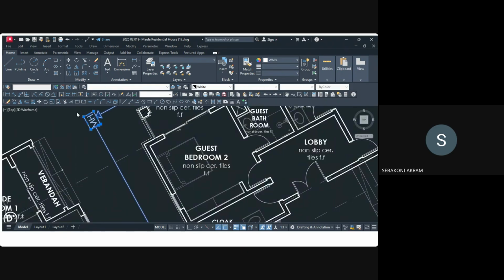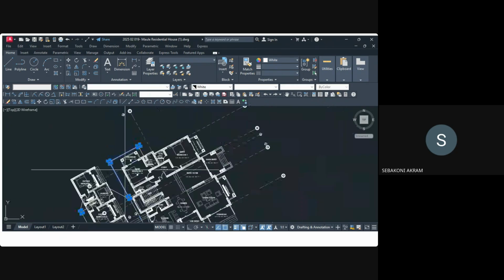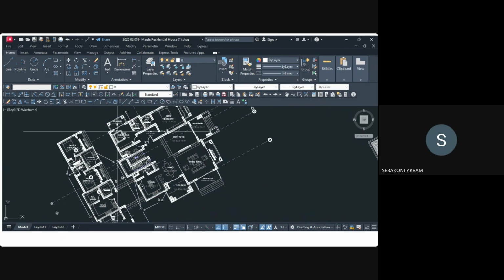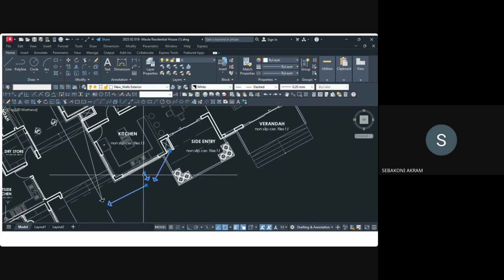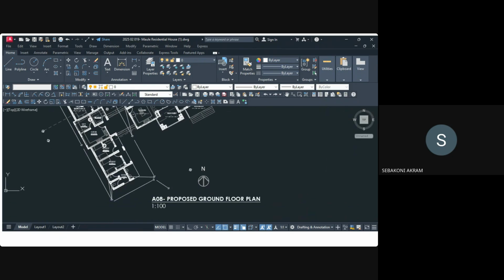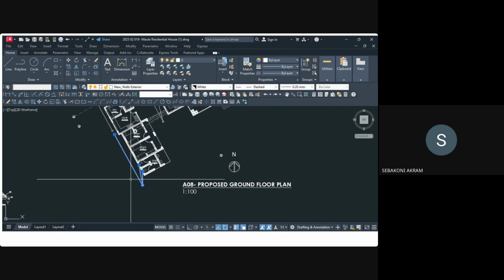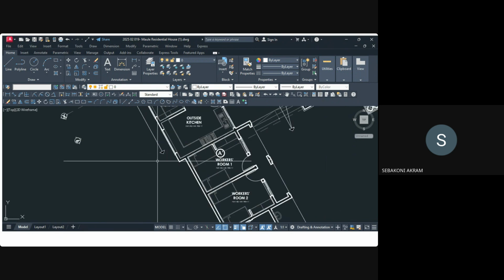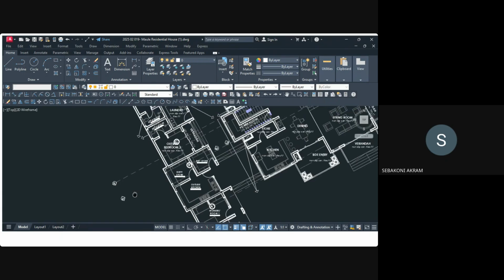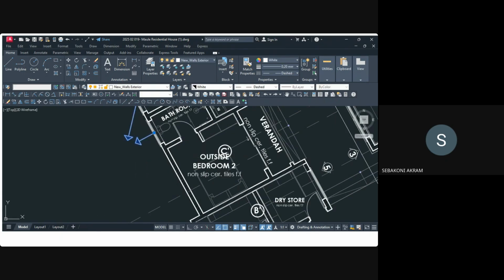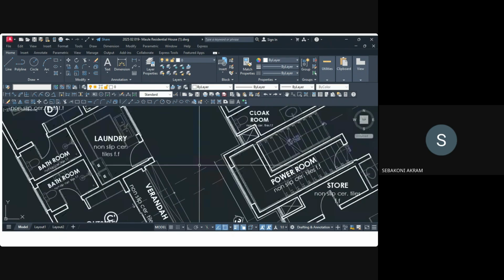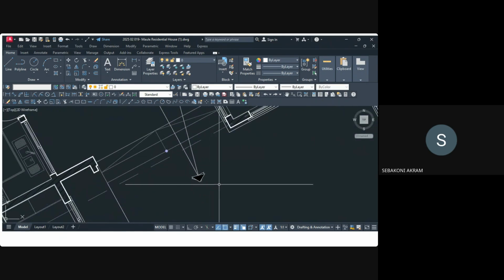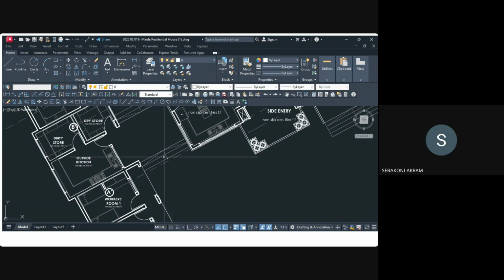You highlight, you delete, you select similar and delete them, because in the electrical drawings there are no manholes. You remember, you're going to use this clean drawing for the electrical and also the plumbing. If the mechanical comes in, you would have to use it too. So we delete all this. The cleaning process is the most important and, I would say, most difficult process, because it's where we analyze the building and remove all the unnecessary information. So this is the most important step in AutoCAD when you're starting.